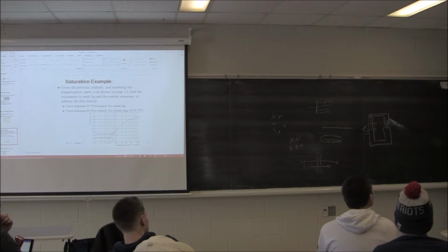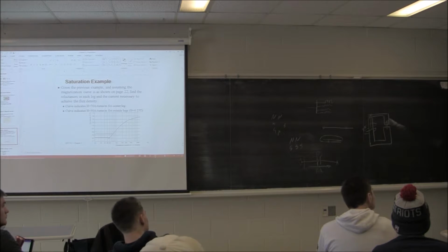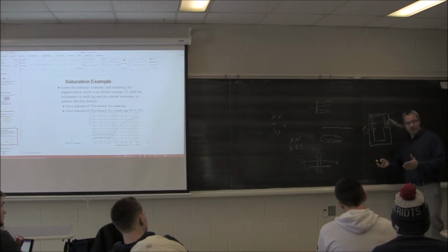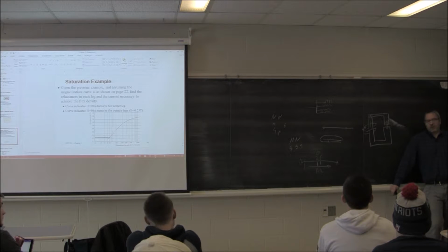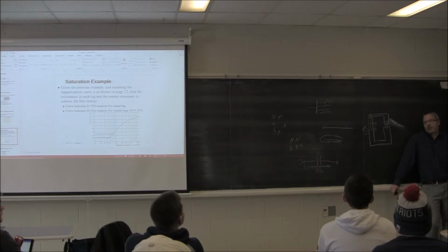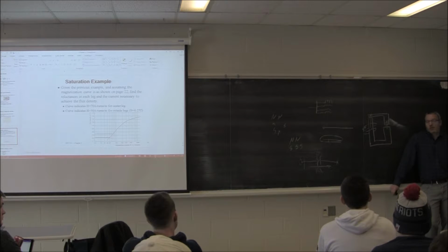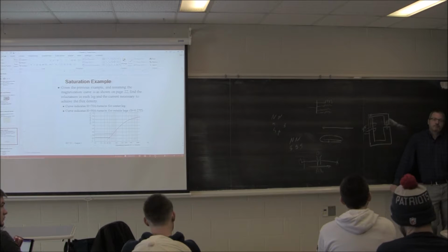They have 5,000 amp service at 208 volts. You probably have 500 MCM conductors per phase. Whereas if you had the 4160 volt transformer right there, you could run in just regular, like number 4-aught wire, is all you would need to be able to handle that current. So that's why they used to do things in the basement. Some of the dorms are that way too.